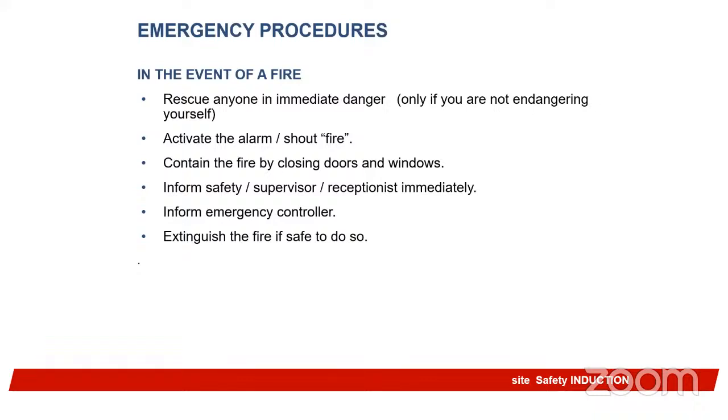So you talk about your emergency procedures. If there's a fire: activate the alarm, call the attention of people, and contain the fire by closing the doors. That is why it's at the design stage. Then we're talking about LOPA, layer of protection, or line of defense, LOD. Those are process safety training. Maybe some other time we might talk about this in other trainings, but we are talking about the basic ones now. So in case there's a fire, at the design stage, all those doors will be intumescent material, so that it will contain the fire, so that people will be able to escape, or those who will attend to the fire will do that at that point in time.